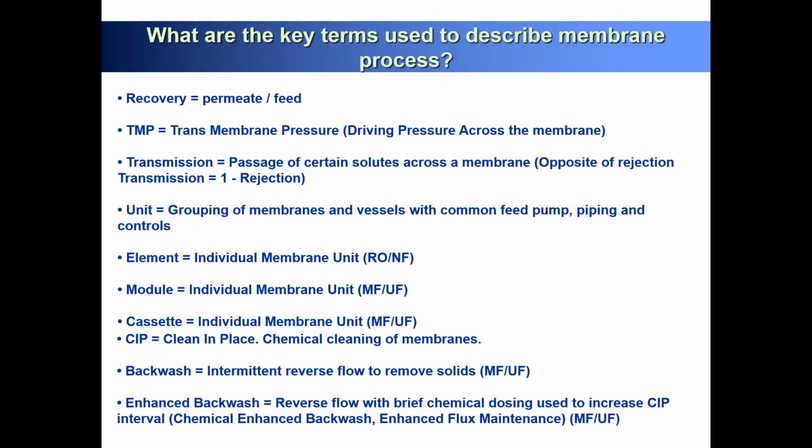So in one module we have a very high surface area of your ultrafiltration membrane surface, which you can use to calculate your overall water loss. So we need to design ultrafiltration as a module, and element is the reverse osmosis membrane.